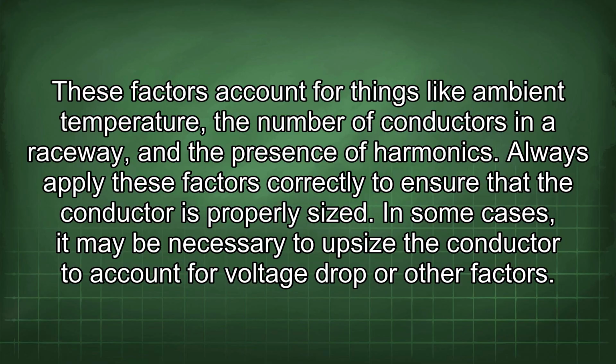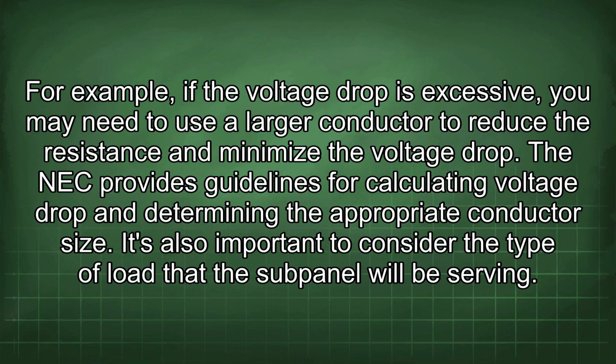In some cases, it may be necessary to upsize the conductor to account for voltage drop or other factors. For example, if the voltage drop is excessive, you may need to use a larger conductor to reduce the resistance and minimize the voltage drop. The NEC provides guidelines for calculating voltage drop and determining the appropriate conductor size.